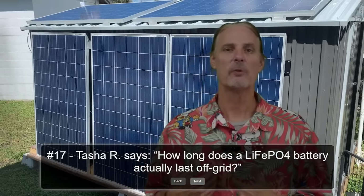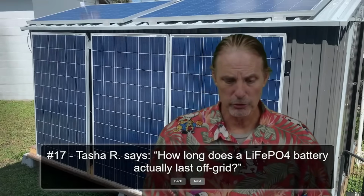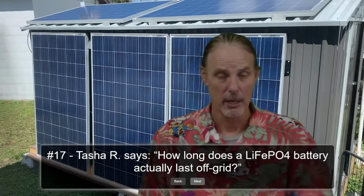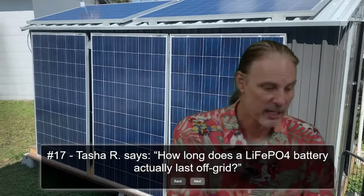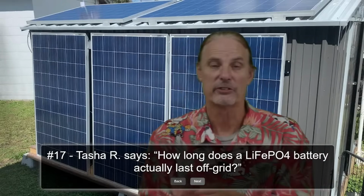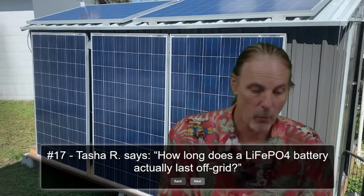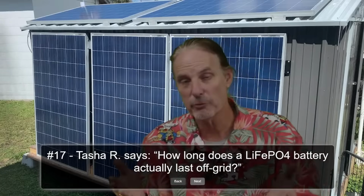In my mind, a cycle means that I pull the battery down, use a certain amount of it, and charge it back up. I would probably say an 80% discharge and recharge should be 1 cycle. Some manufacturers use 100%. So they say if I've got the battery going up and down to 50% twice, then that counts as a cycle. Some manufacturers use less than that. They say 80% depth of discharge. So they say if I go from 100% to 60%, back up to 100%, back down to 60%, that's 1 cycle.